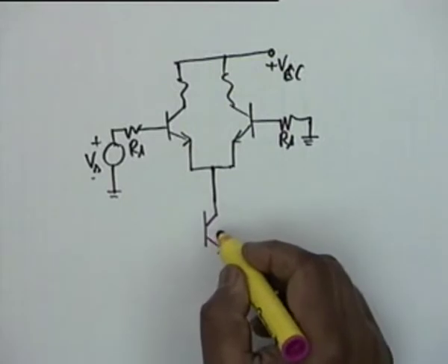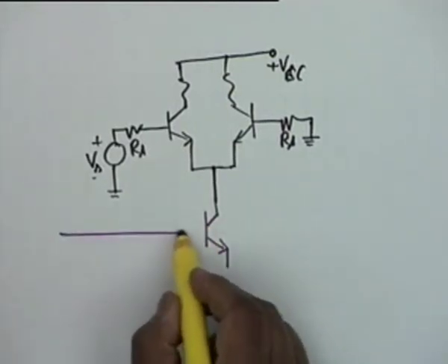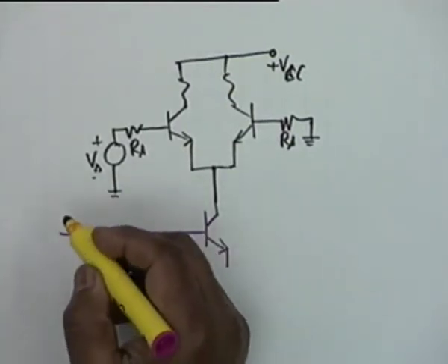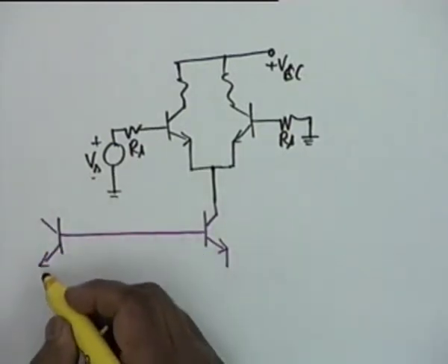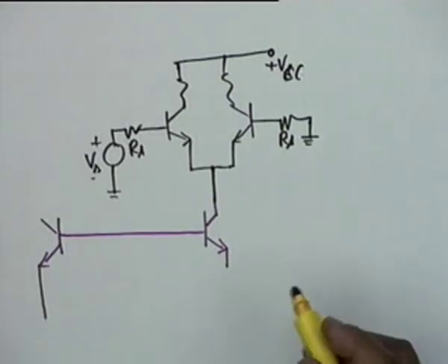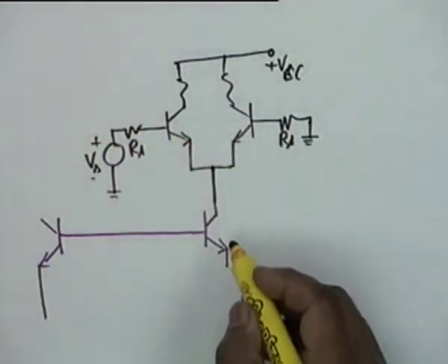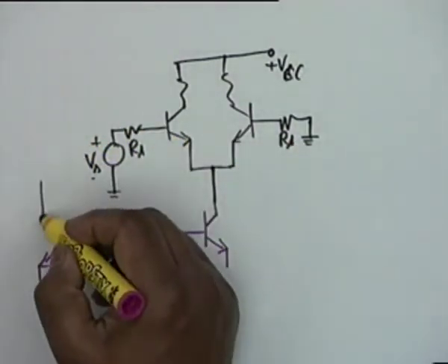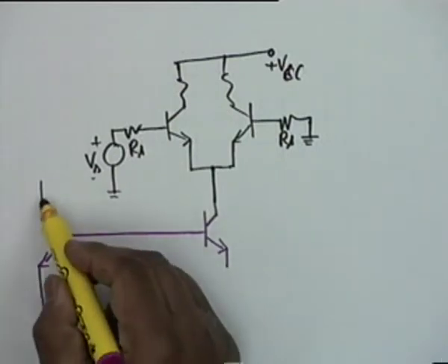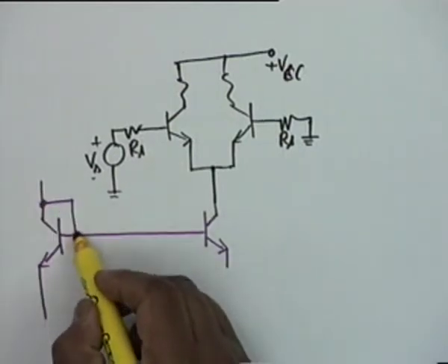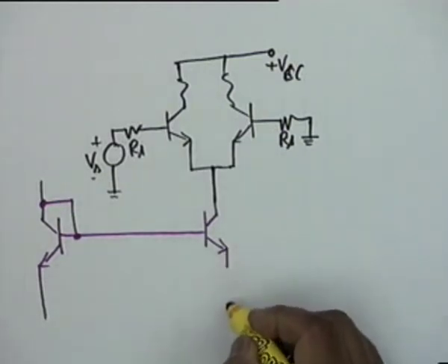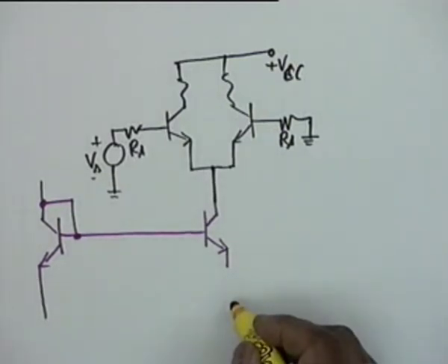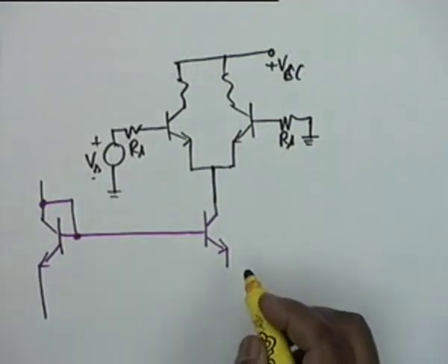Okay, what you have is, now what we have to do is two transistors. The reference transistor has to have its collector connected to the base, agreed, and these two emitters should come together if it is a simple current source.